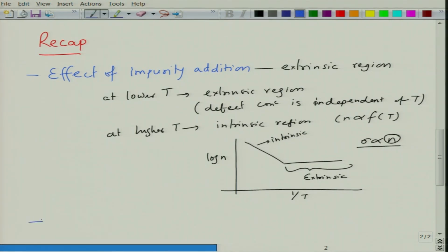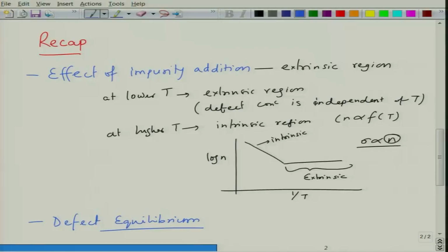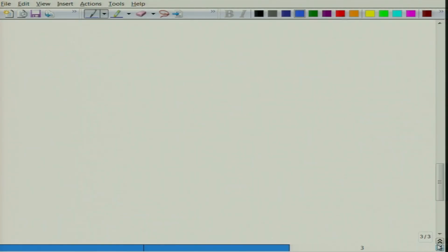And then we looked at the defect equilibrium. Basically we wanted to establish conditions as a function of ambient conditions. In the case of stoichiometric solids or stoichiometric defects, the concentration of defects depends upon temperature only, it does not depend upon conditions like the partial pressure of oxygen. And whether the denominator is 2 kT, 3 kT or 4 kT will depend upon the stoichiometry of the oxide. So, for MO it would be 2 kT, but for M2O3 and MO2 it could be different. Let us now further dwell upon the same thing.